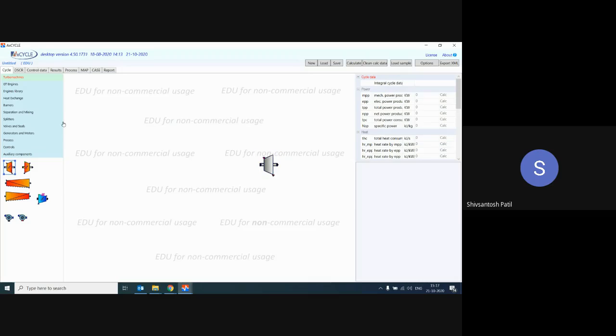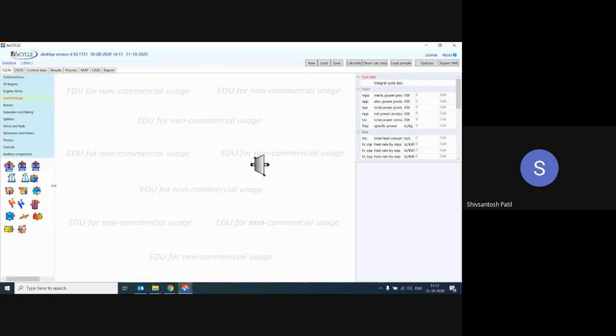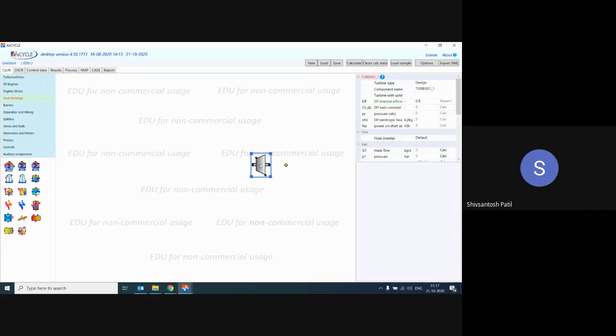add it. After the turbine, for example, I go to my relevant element, then I will require a boiler. So you just go to this boiler library. You can expand this, okay, like this. You can see it expands as per your convenience. You can zoom this, like you click here, press on A, you can expand this, as well as zoom in, zoom out by pressing the control button, and you can move your cursor with the center button. Okay, you can rotate that and zoom in, zoom out easily like Windows function.